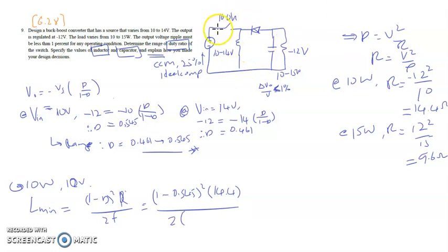Because the switching frequency has not been indicated in the question, an assumption can be made. You can use 50 kilohertz, 100 kilohertz, or 30 kilohertz. So the range is between 20 kilohertz and maybe up to 500 kilohertz. We cannot use more than that, because in power switching we will have more losses at higher switching frequency. If you use below 20 kilohertz, you will introduce an audible noise issue. So we just put 100 kilohertz as our chosen value.